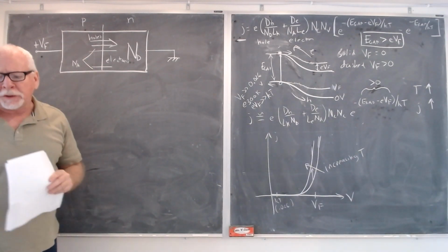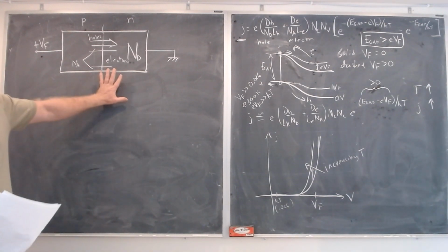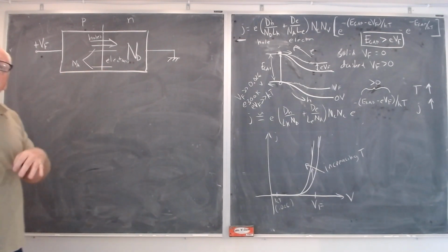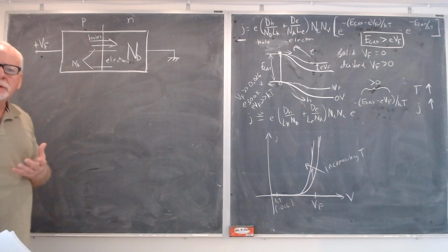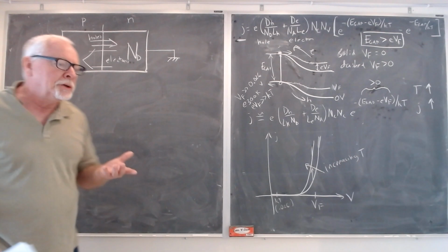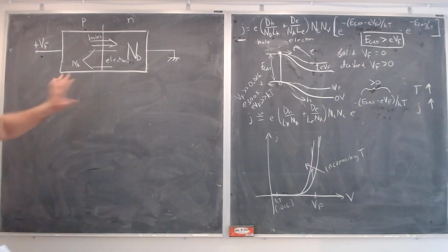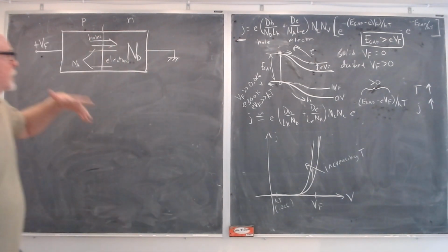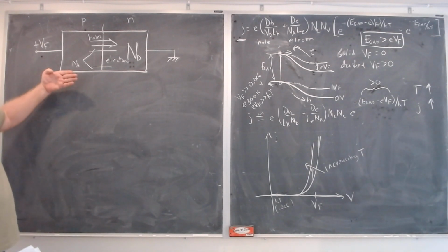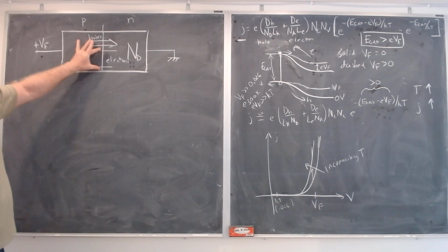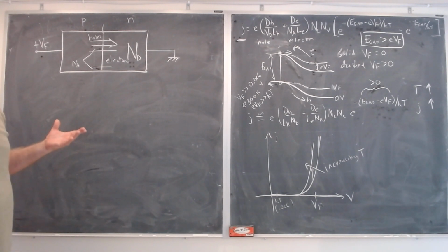So this is where I'm going to end this lecture, because we have to understand this principle in order to do the next device, which flows from PN diodes, which is the bipolar transistor. I'm not going to get started on a bipolar transistor today, but I want you to remember this picture that comes directly from the equation, and also just reasoning that if I dope one side lower than the other, I can get an asymmetric distribution of hole and electron flow in my total current.